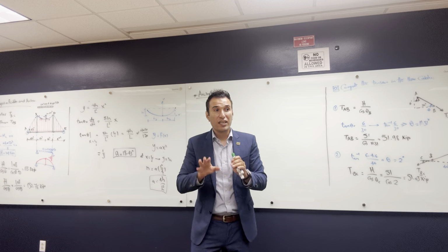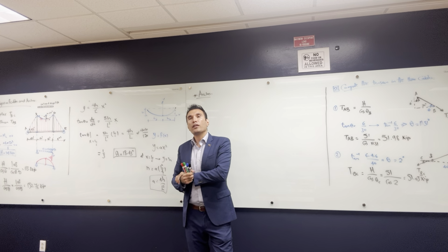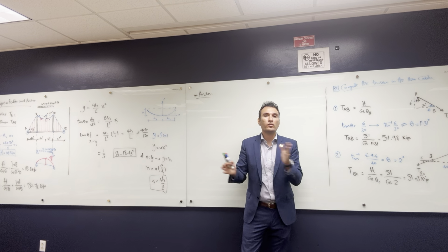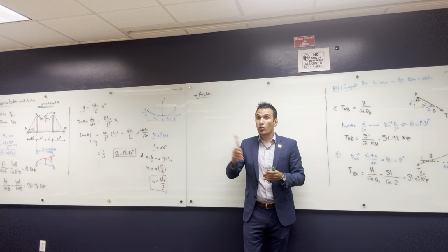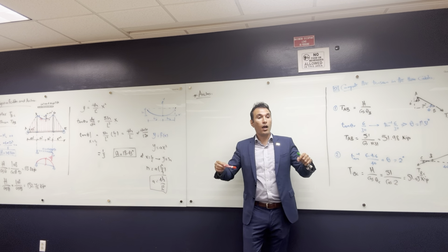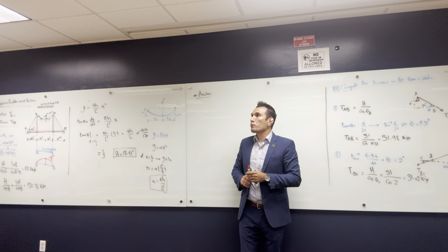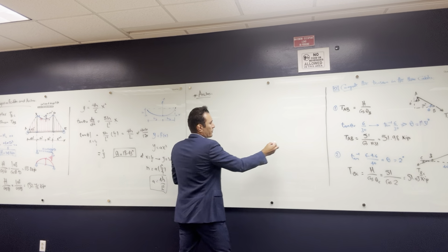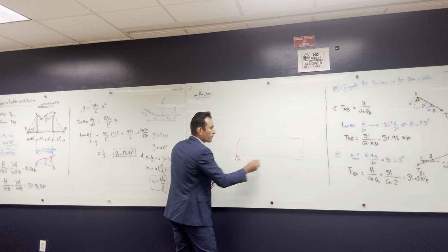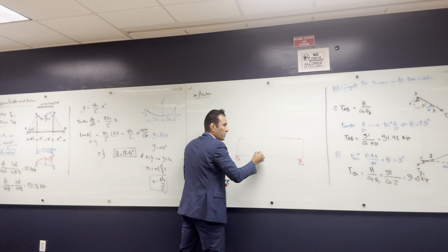Okay, so as engineers, we wanna get rid of the bending moment. So that's why, okay, let me ask you, what systems don't have bending moment or have almost 0 bending moments? Trusses, right? We use trusses because they have tension and compression, and this tries to make the bending moment 0, okay? But with trusses, rather than having a beam like this to hold your system, and you put all these materials inside, you only need tension here and compression here.